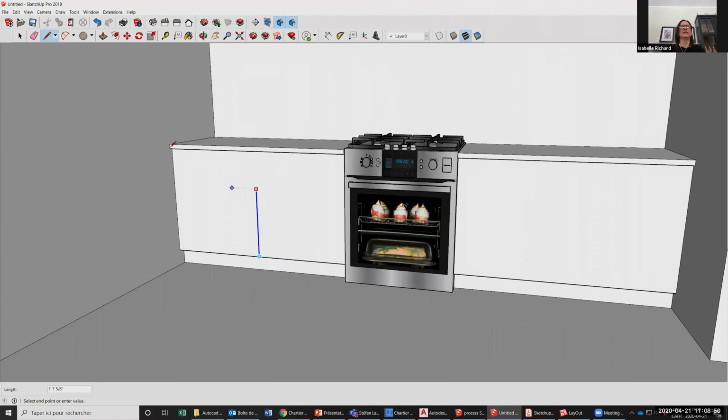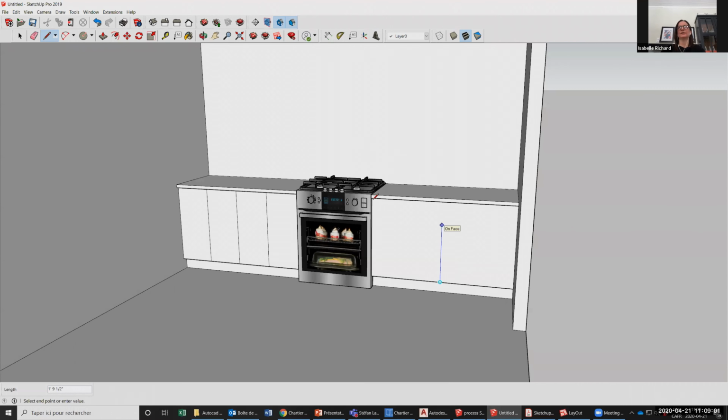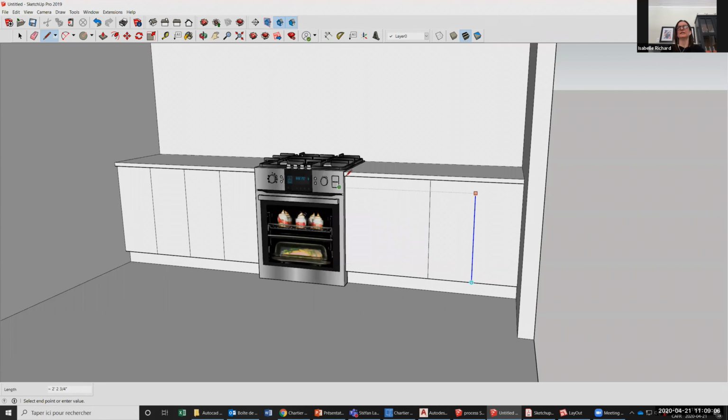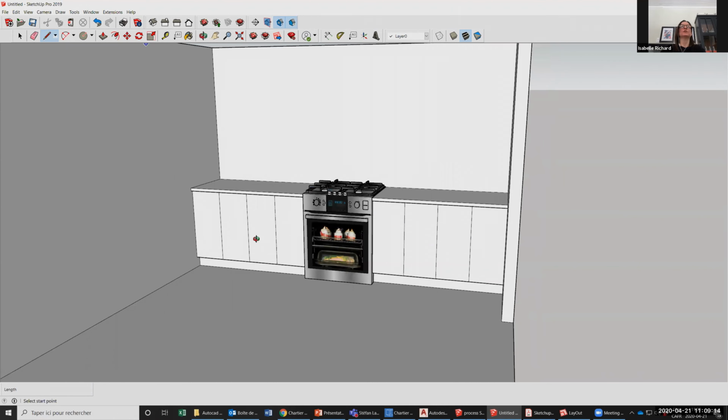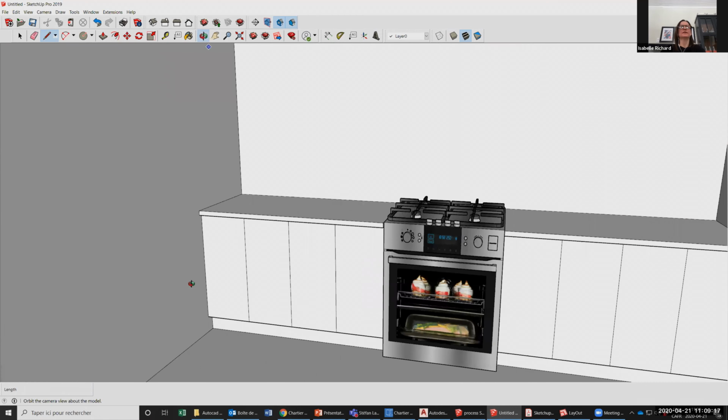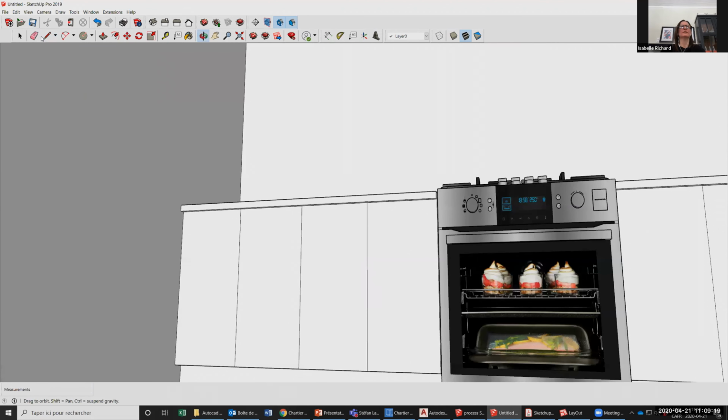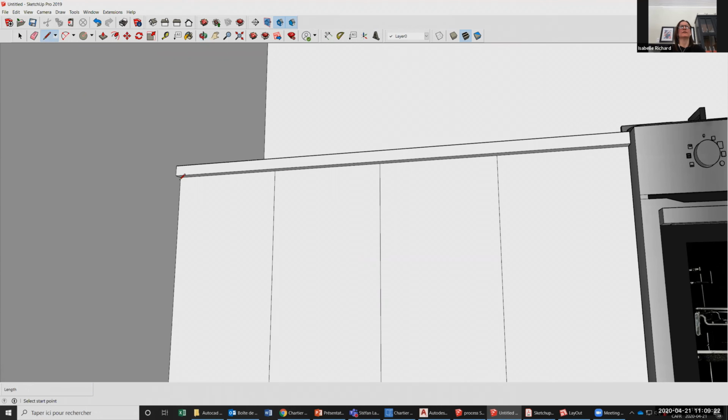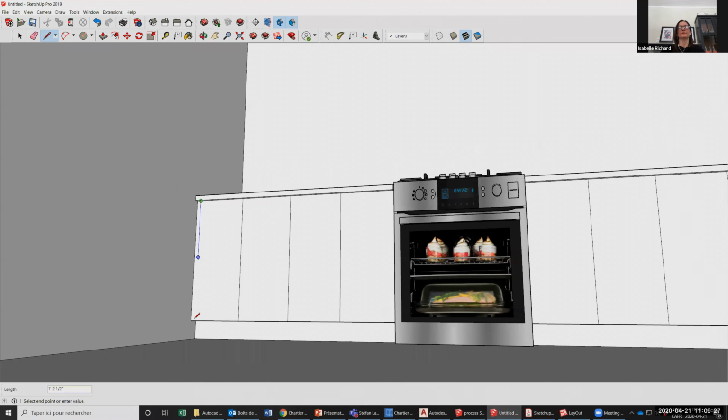So I want to just separate my faces to make doors in equal parts. So I just go from the midpoint and then draw over the faces. And this way I have the outline of a door, right? So if I want to make drawers on the top part of my cabinets, we can also draw the fillers, right?